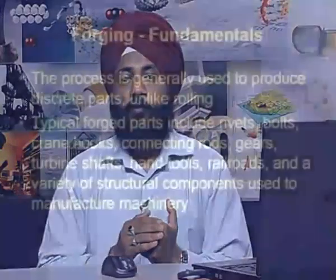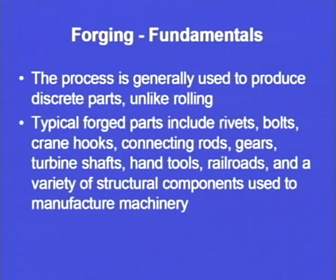Now, the applications of forging: what are the different types of parts that can be manufactured using the process of forging? Typical forged parts include rivets, bolts, already I have given one example, crane hooks, connecting rods, gears, turbine shafts, hand tools, railroads and a variety of structural components used to manufacture machinery. So, different types of machine components can be made using the process of forging.